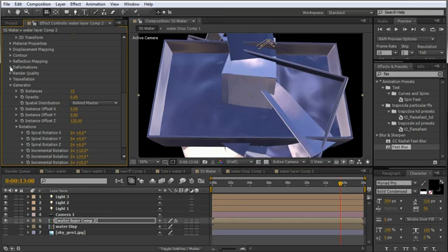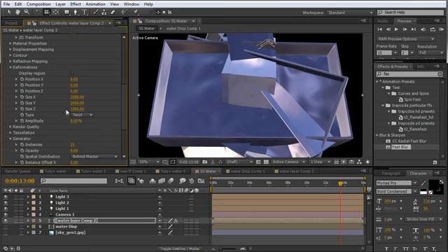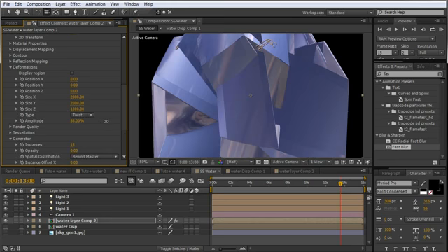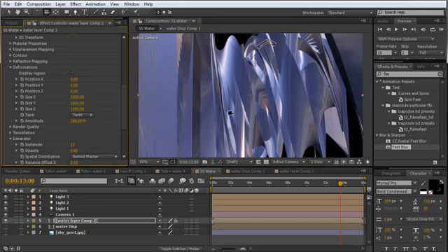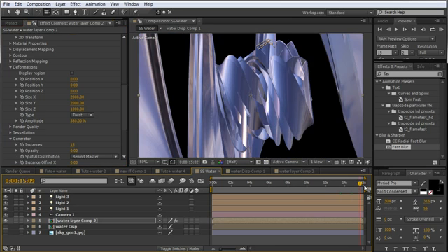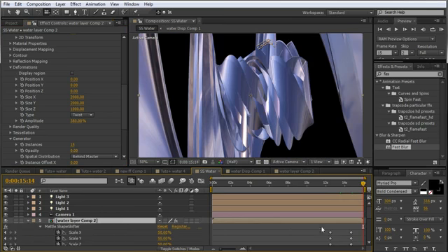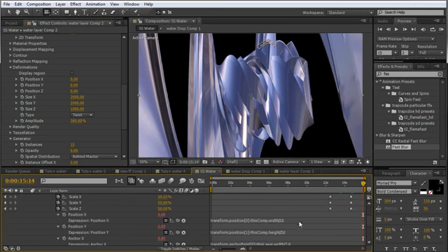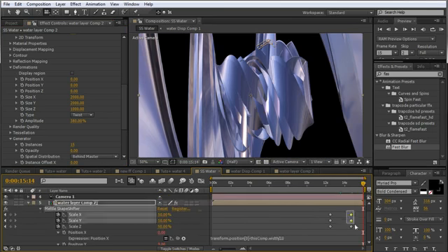Now I'm going to go to deformations, and deformations is something that's available in Shapeshifter. This isn't available in Freeform Pro, but in Freeform Pro at this point you can come and start messing around with the control points and get some kind of interesting looks pretty easily with those. And this is actually what I'm going to use for our example today. Let me come up here. I'm going to press U and start adjusting everything.